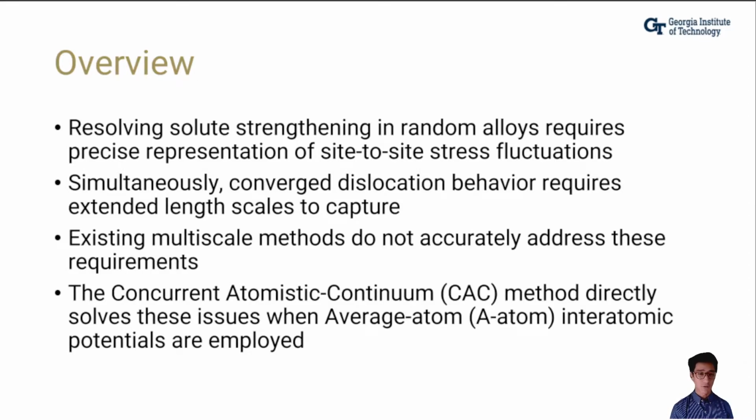In this talk, I will describe our recent efforts to model dislocation mechanisms in a concurrent multi-scale modeling framework, the concurrent atomistic continuum approach.